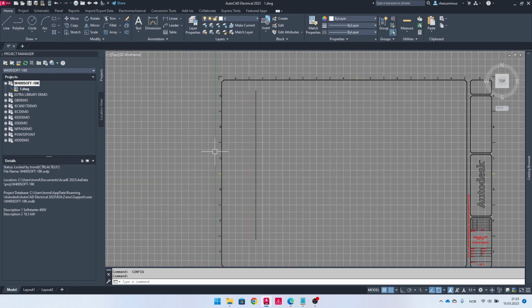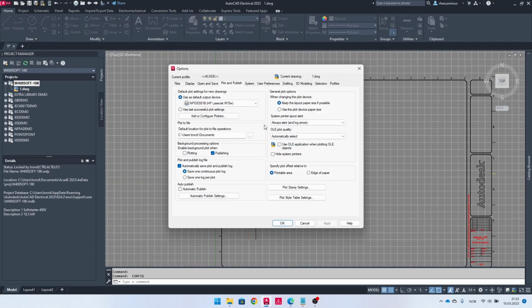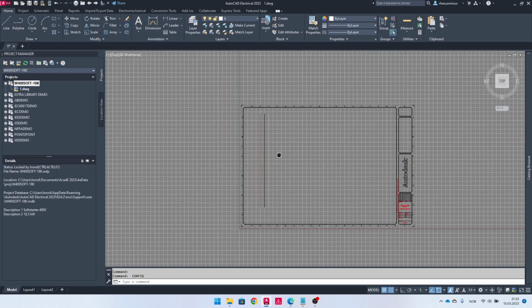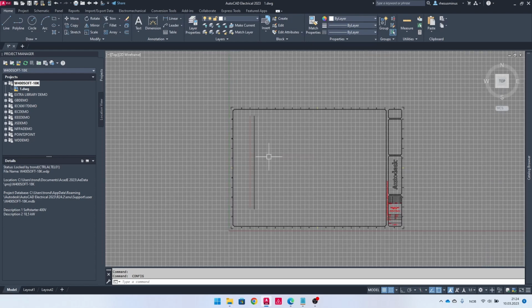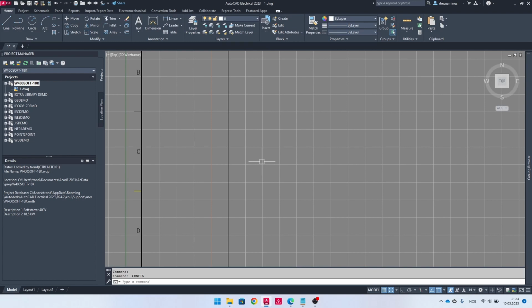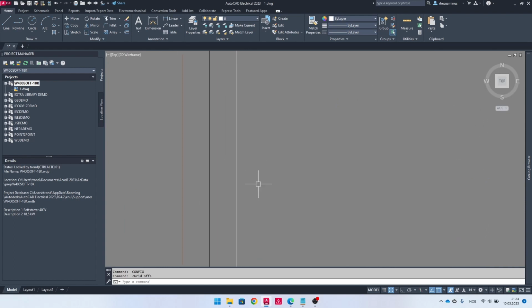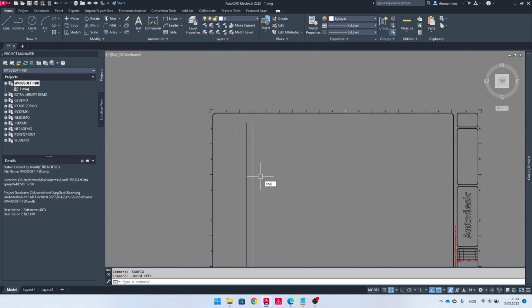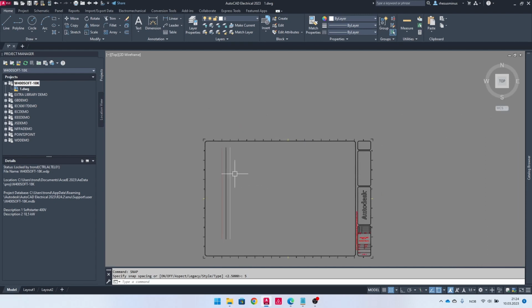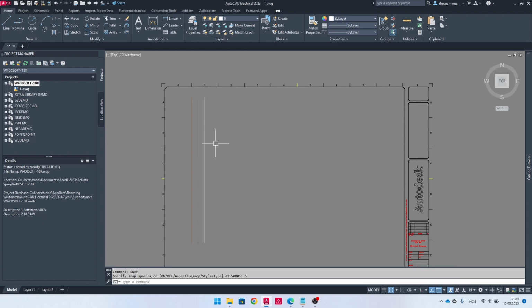That was a terrible combination, but yeah, I'll just turn off the grid for now maybe. Yep, looks better. Also, snap would be like 5 millimeters, because the spacing is 10 millimeters between everything, so 5 would work just fine. So let's just start with the terminals then on top there.